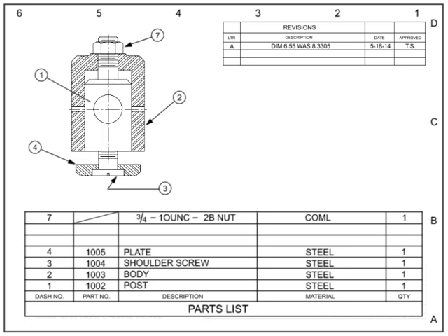At a minimum, the parts list should indicate the quantity of parts per assembly, the part identifying number, and the nomenclature or description of the item. Most parts lists also include a material or finish description as well. Most modern drawing standards also require a dash number which helps locate the part in the field of the drawing. This item number is referenced both in the parts list and in the field of the drawing to identify the part.